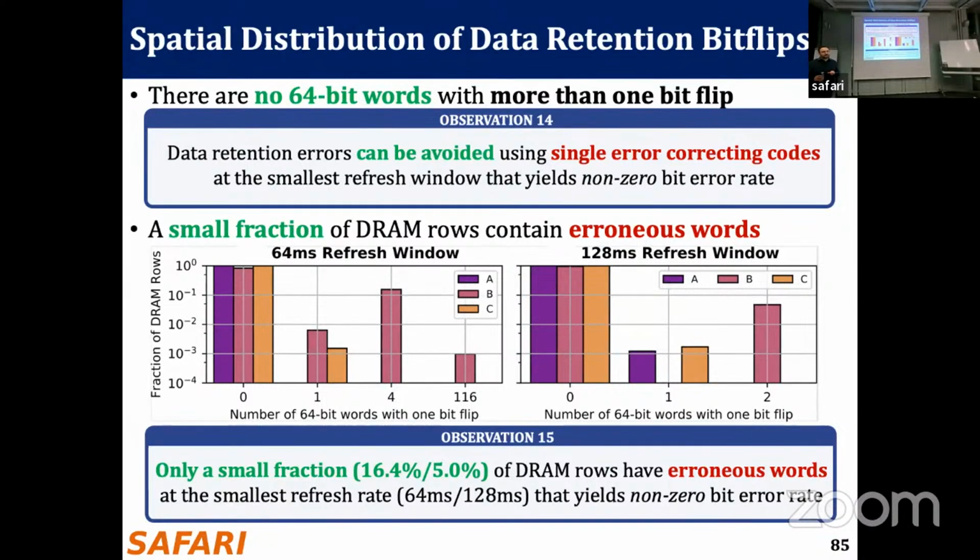So another general takeaway we get from this work was that yes, we reduced the RowHammer vulnerability, but the reduction is not really strong, even when we go to very low wordline voltage. So in the middle, it will be an even weaker reduction. Yeah. So if it affects the data retention time less, then it affects the data disturbance as well. Yeah. Data disturbance.